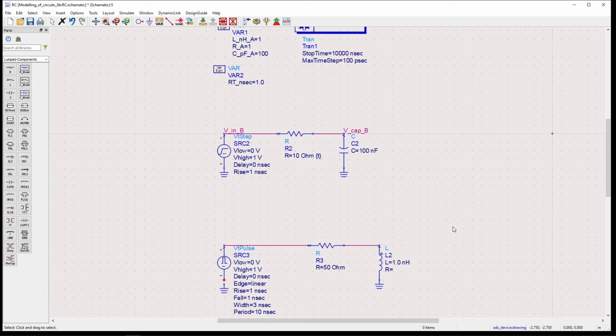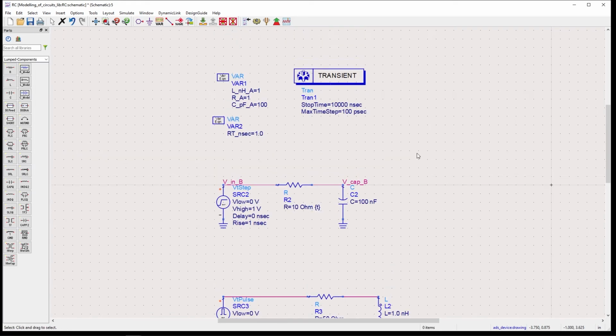One thing to note with something like ADS, when you're doing a transient response, is that you need to know how quickly your step response is and specify your stop time. If you put a very large number, even 1 second, because you're doing transient response, 1 second is a huge number for these types of analysis. It can take a long time to simulate, because we are simulating at picoseconds. Anyways, what I'm going to do is run the simulation, and once it's done,